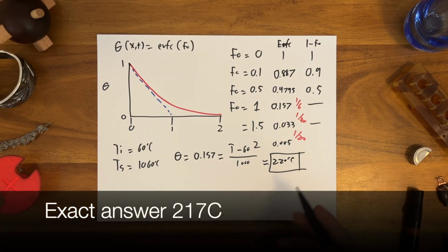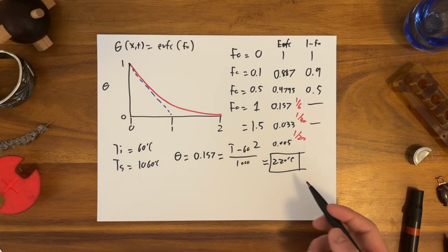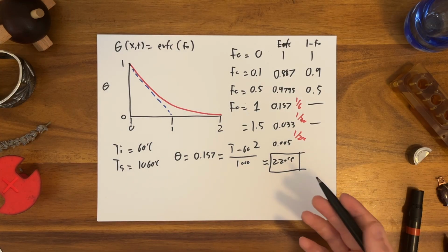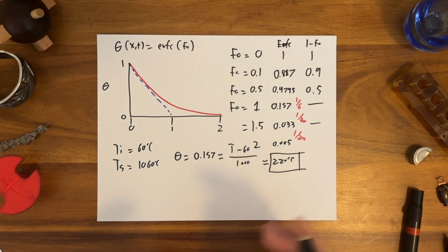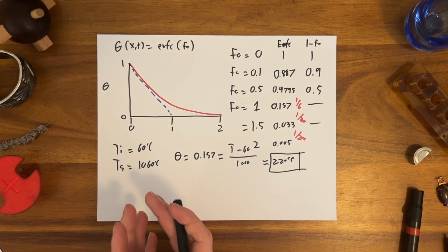And that's fine. Like I can have an aluminum that hits 220 C. It'll lose about half of its strength. It'll still be there. It's not molten. So this is actually a pretty good insulator. Taking the 1,000 Celsius and chopping it down to 220, pretty reasonable.